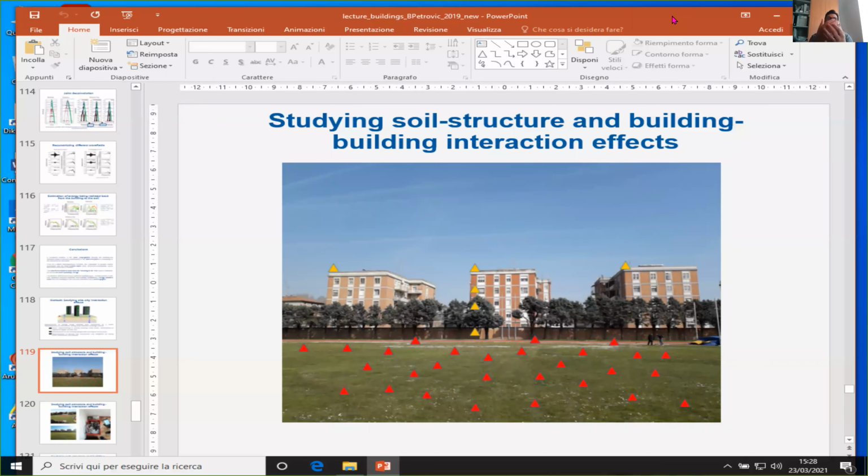And I mean, the reduction of amplitude in the amplitude spectrum is one question. You can reproduce this reduction of amplitude over a spectrum, maybe with the apparent one, and that's fine. But if you take the apparent one as intrinsic and you try to reproduce time series, this will introduce a large bias, maybe not only on the amplitude of shaking, but especially on the duration, which is very important. And this is really one of the main issues that we have at the moment. It's really a big issue. It's not easy to be solved.